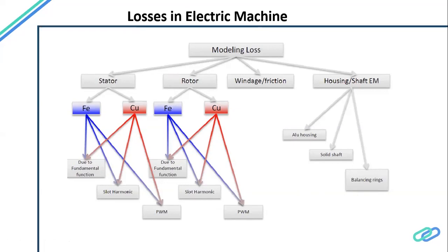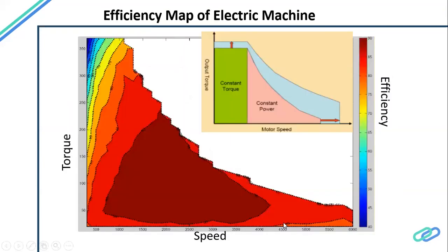We have to be very careful what kind of other harmonics are getting injected into the machine, because those are either producing negative torque, or producing I squared R loss, or increasing iron losses, because iron losses are very much driven by the frequencies that we have. So with higher harmonics and higher frequencies, those losses will be impacted. So harmonics are at center stage when we talk about it.